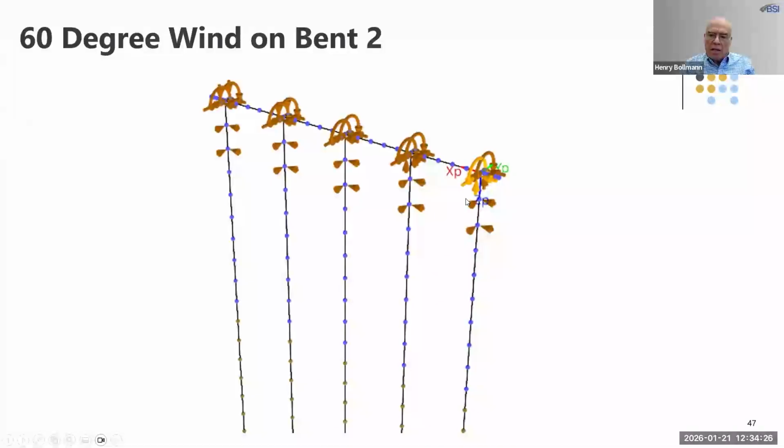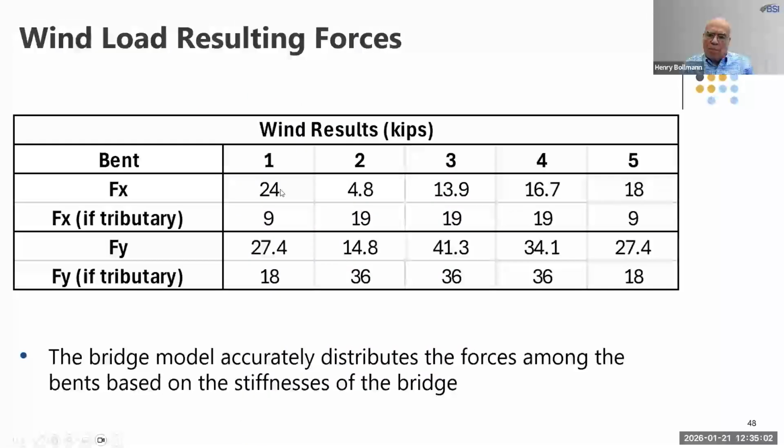And then you get a picture of the wind load vectors. So I can see here that I've got vectors on all these piles. That's good. And of course you can zoom in and blow this up and see it a little bit better, but it shows overturning bending moments longitudinally. Here you see some vertical forces, down and down here, some vertical up forces. So those are the overturning forces because we have positive wind in the X direction. We have wind in the Y direction, so we got overturning moments in that direction. So this gives you a feeling that everything's looking right.